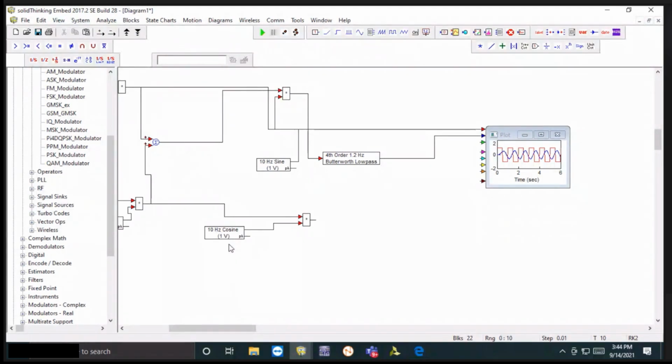So that will allow the 1 into message signal component to pass, and cos 2A will be a high frequency signal that will be filtered out. A normal synchronous detection method that we have applied for the DSBSC case, right? So the same thing will apply here to extract our message signal back.